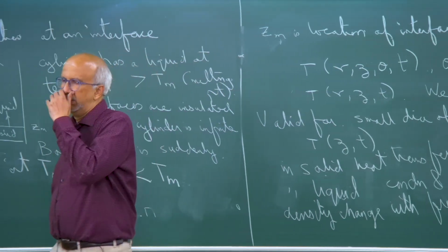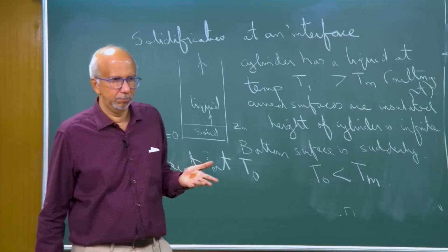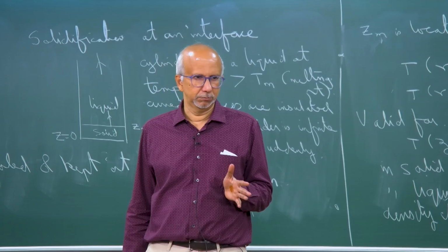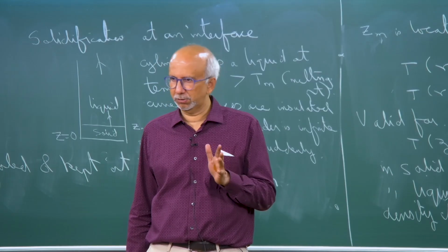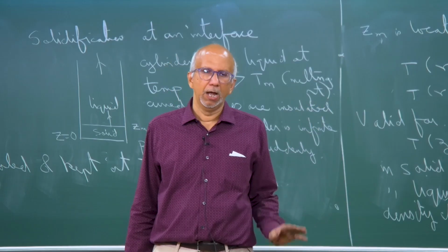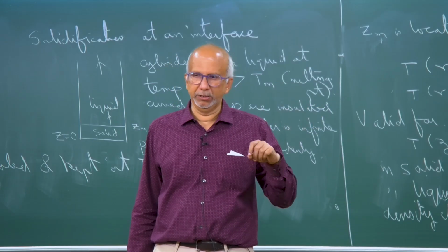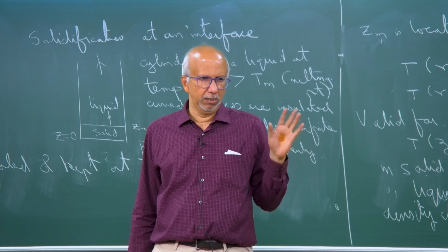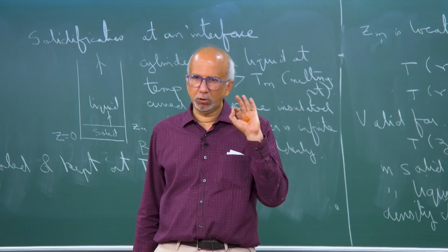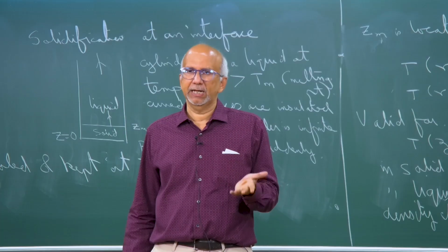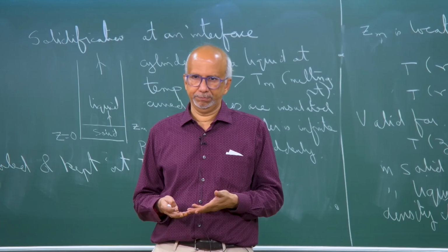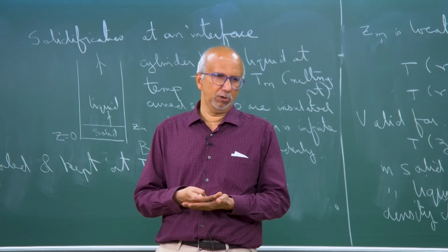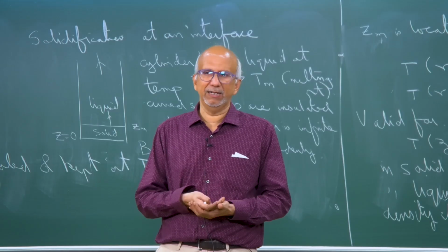Okay. So, I am going to be a nice guy and just going to assume that the density does not change. Okay. So, we will just not worry about convection in the liquid. But even if you include convection, whatever I am doing, you can extend it and you can do the same analysis. Okay. So, I just wanted to inform you that right now I am going to assume that there is no phase change, which means there is going to be no convection induced in the liquid. Okay. Only conduction. So, I am going to have only conduction, again this is an assumption I am making. I am going to assume only conduction in the liquid and in the solid.